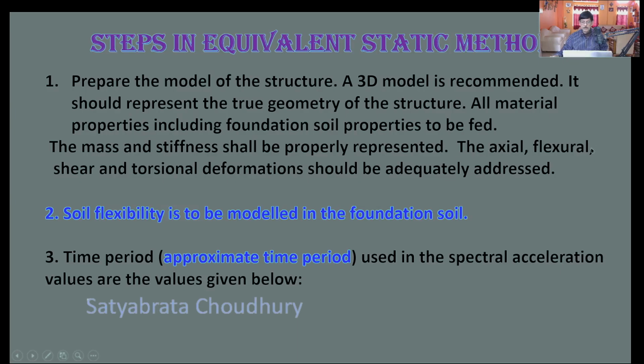The axial, flexural, shear and torsional deformation should be adequately addressed in the model. Soil flexibility is to be modeled in the foundation soil. For that purpose, the code has given the stiffness of the springs of the soil to be used in the foundation. There are certain vertical springs, some horizontal springs, some rotational springs. These spring constants are given in terms of the modulus of subgrade reaction of the soil.